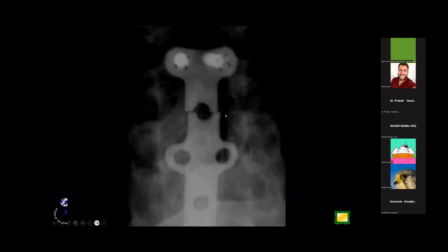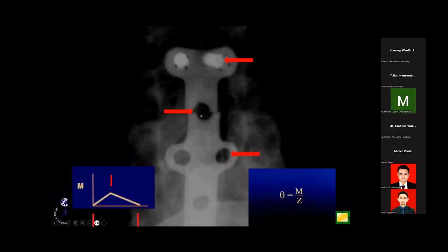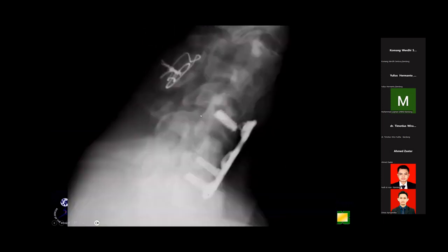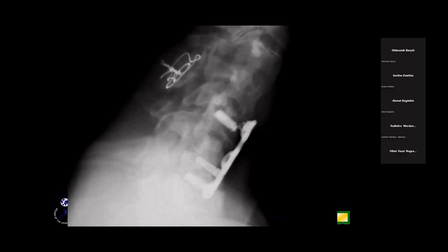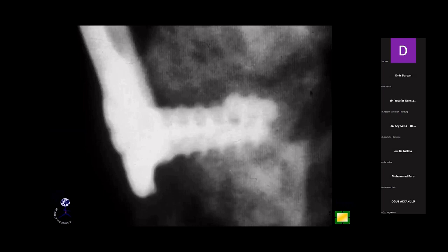This is a very weak portion of the rod, or the plate, so the strength is small, and the loads can be great. So this is a screw that fractured at the plate. It is a constant inner diameter screw. This screw is a tapered inner diameter screw and fractured distally.